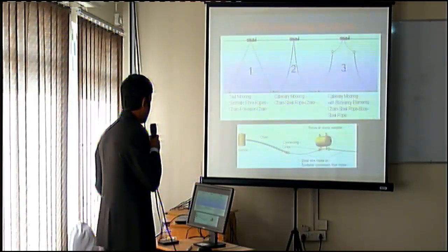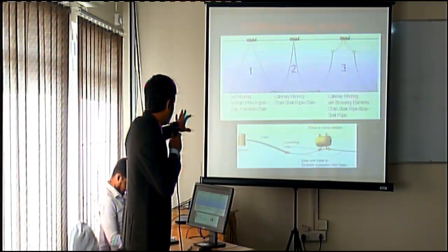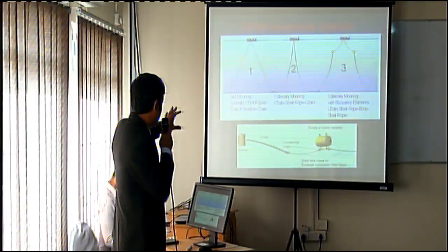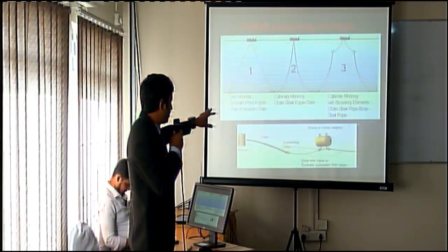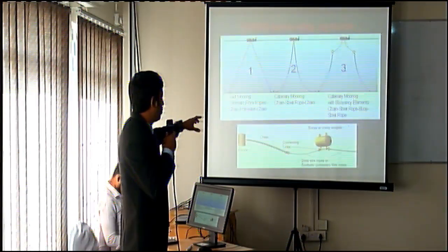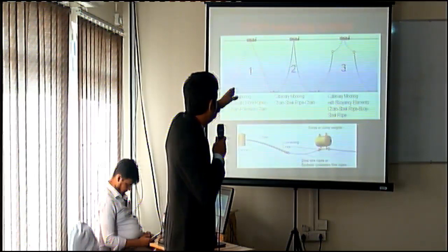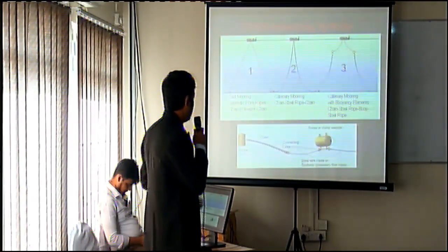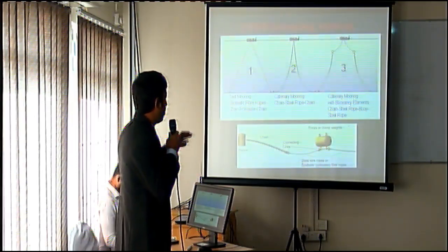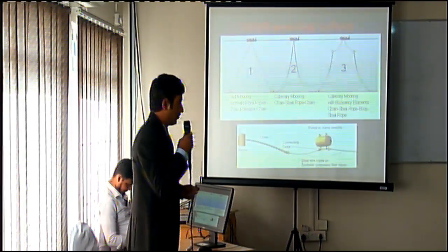And here are the types of mooring systems that we have already available. One is taut mooring. It's a kind of synthetic fiber rope that we can use. They're pretty much stiff. We also have the catenary mooring system, which comprises chain, steel rope, and also chain. That means at the seabed you will put chain and then some steel rope, and on the upper side you will still have chain. Another type of catenary mooring uses buoys on the chain to give some extra buoyancy.